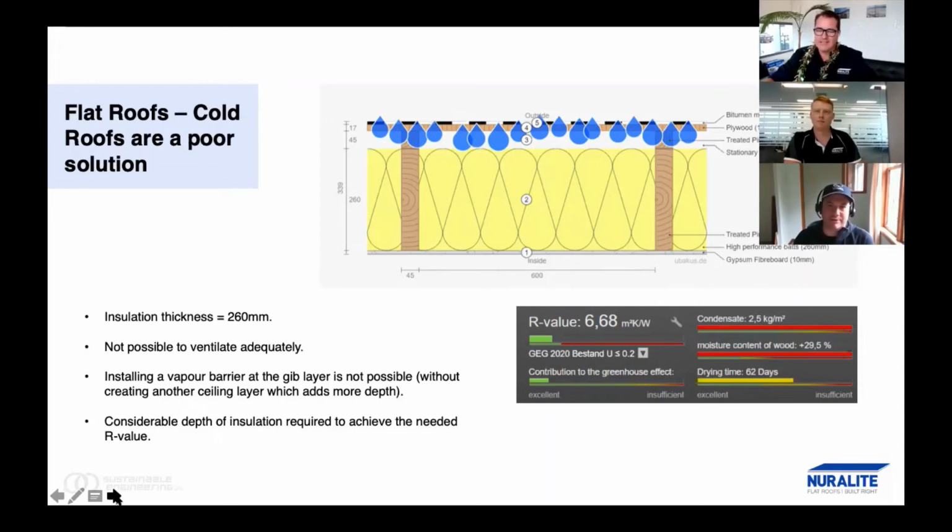It's easy for designers to draw a roof with a venting and say there's a mushroom vent per 40 square meters, the way the specs say, right? It's easy to draw that, but the poor builder, when he's putting it in, he's got to put blocking in at the edge of the sheets. And then, you know, there's a skylight somewhere that causes blocking problems. It really pushes the risk and the difficulty onto the builder, and I don't think it's appropriate anymore. Yeah, and typically you'd have timber running 400 centers both ways. So you're creating these little cells. So you'd almost have a vent every 400 millimeter square, which would have a unique look, I guess.